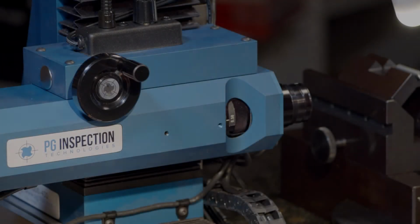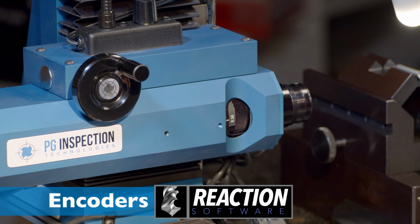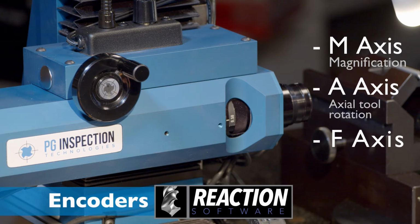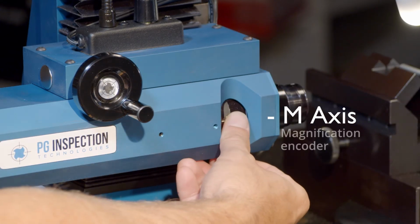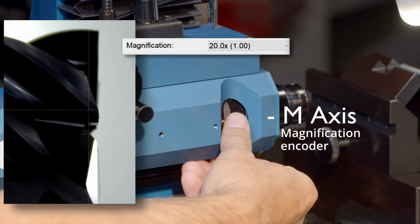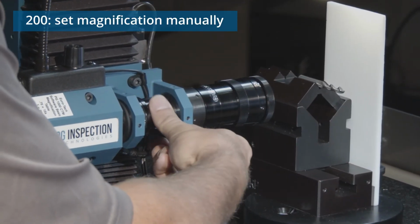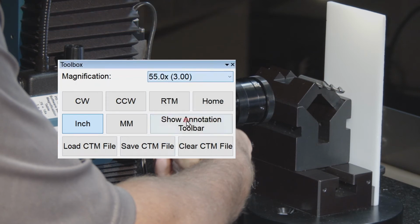Unlike the 200, the 400 has built-in encoders which automatically report, record, and display measurement data directly to the system software. In addition to X and Y parameters, the 400 acquires magnification data, the angle of tool rotation, and focus data. First of all, the M-axis. The 400 has a magnetic encoder which will automatically synchronize the scope magnification with the software. The PG1000 200 doesn't have that encoder, so scope magnification in the software must be manually switched by the user to match the physical magnification of the microscope.